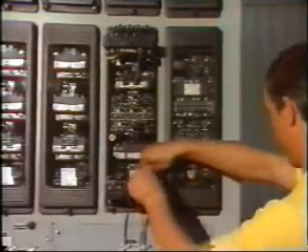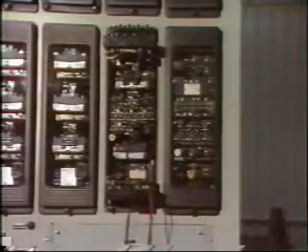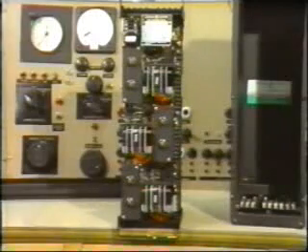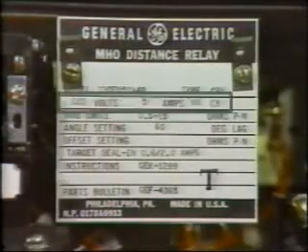This provides significant protection to the relay and also to personnel working on the protection equipment. Low voltage and current also permit the relay equipment to be made small and precise. Typically, the relay will work at, say, 5 amps and 120 volts.